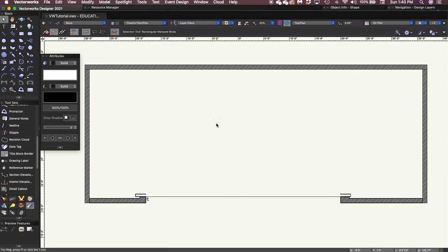Okay, so the next thing we need to do is put in our center line. Remember, all theaters reference off of a plaster line center line, so we can do our point coordinates and everybody's referencing the same origin. So I'm going to select my line tool from the basic tool set. In this case, I'm going to hit the number 2 because I know that that's my shortcut. And I'm going to find the midpoint of the plaster line. I'm going to click once, holding shift to lock my orientation, going straight up until I get to object vertical, and I'll click again, and I have inserted that line.